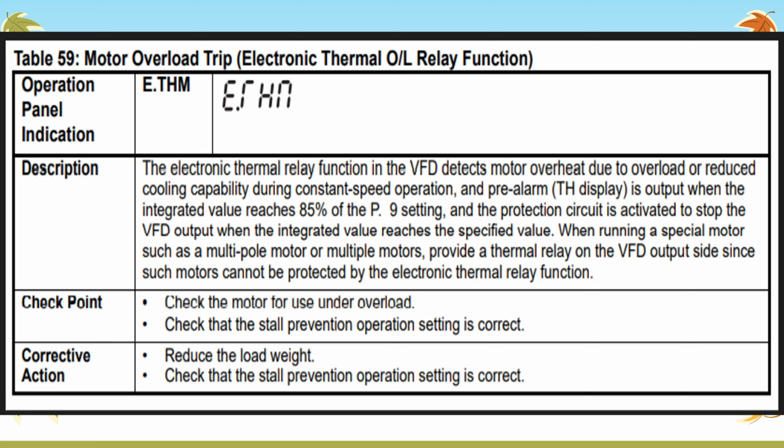When running a special motor such as a multi-pole motor or multiple motors, provide a thermal relay on the VFD output side, since such motors cannot be protected by the electronic thermal relay function. In that case, please check the motor for use under overload, and check that the stall prevention operation setting is correct. Reduce the load and check the stall prevention operation setting. With this you will resolve this issue.